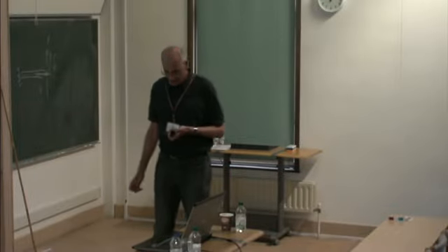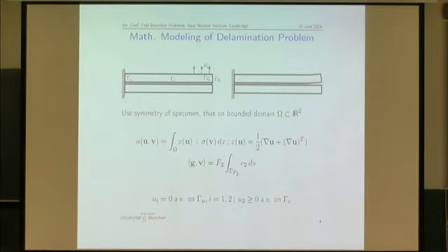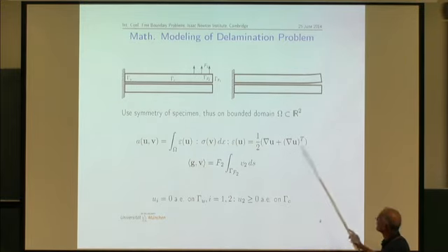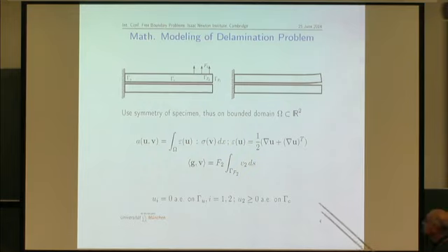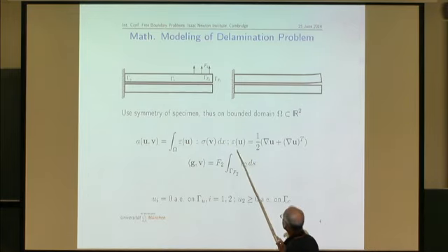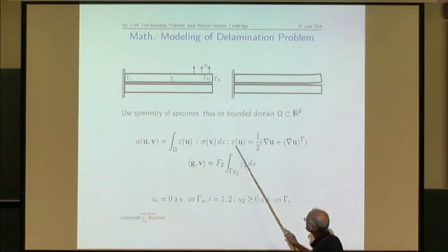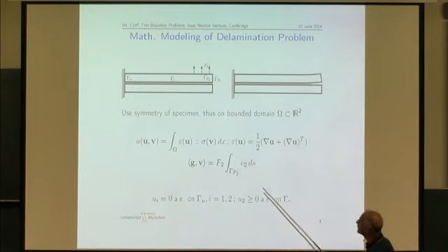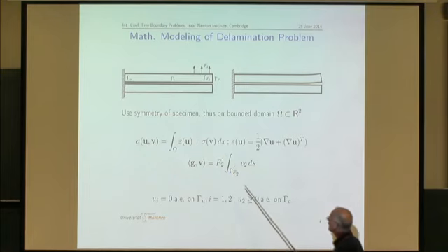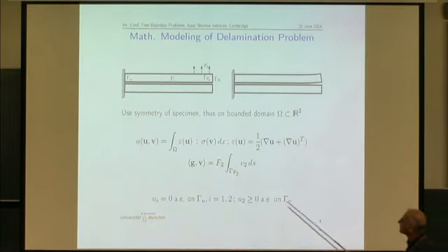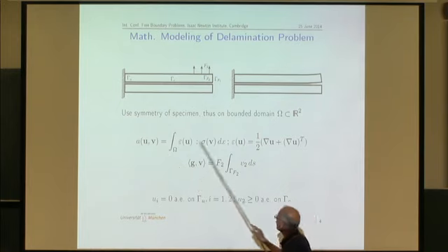So this is where modeling comes in, and we are modeling this problem by continuum mechanics within the range of linear elasticity. So it's a geometric linearization. You have the strain field depending on the displacement field. You have the stress field. This gives you the energy form here.